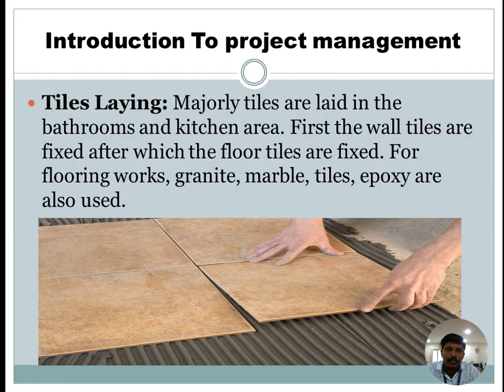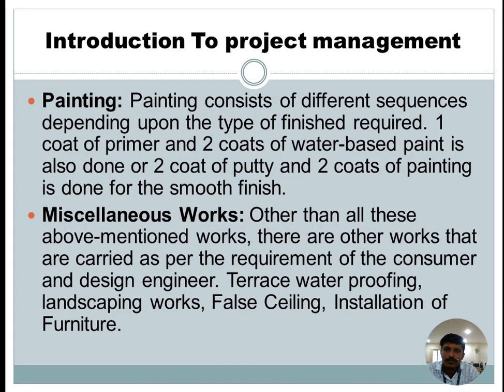Granite, marble tiles and epoxy are also used. These are the different types of materials used in tiles laying work. First of all fix the wall tiles, then start the floor tiles, for smooth finishing of the work.